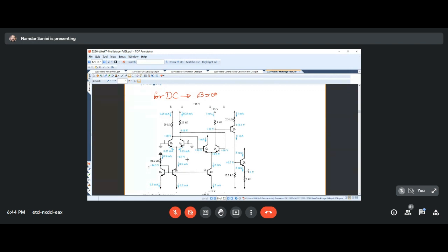Now, we had to find a place where we had all the information we needed for the analysis, and that was this DC bias circuitry. We started by analyzing the current mirror current source, which would give us the current demanded from the emitters. It would split in two parts, and also go up to the collector resistances, dropping a voltage across them.